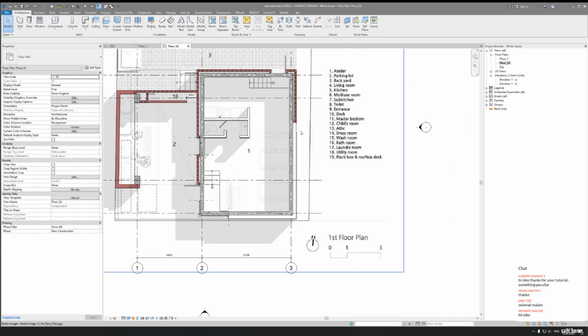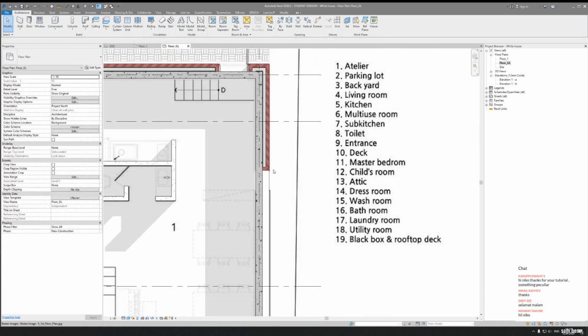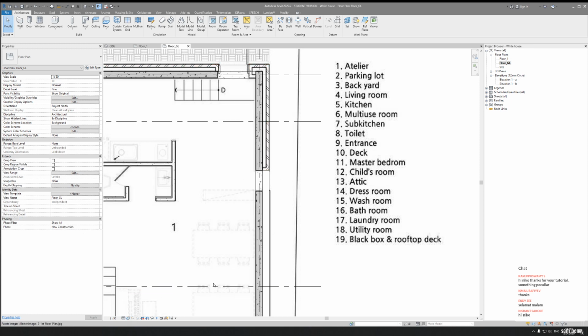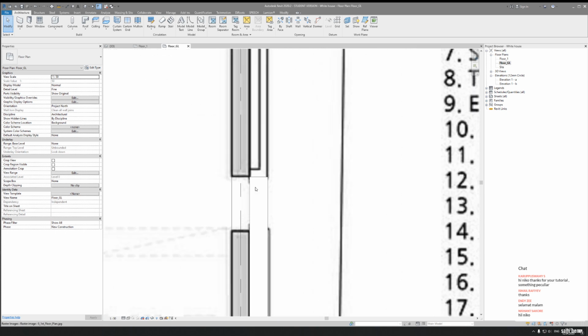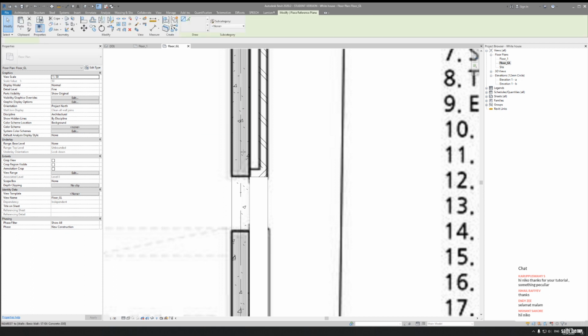And some window we have on this side. As you can see, I cannot see properly now where my windows are, because with our underlay it's covered by our walls. Don't use specific things, or don't use filters. You can just change your graphic to the wireframe mode and you will directly see where your window is. For example, my window is here, and let's draw our reference line.